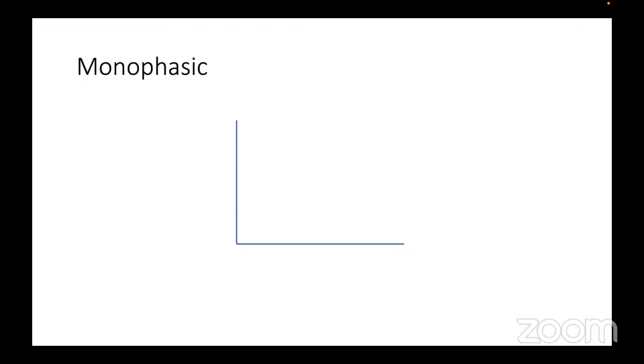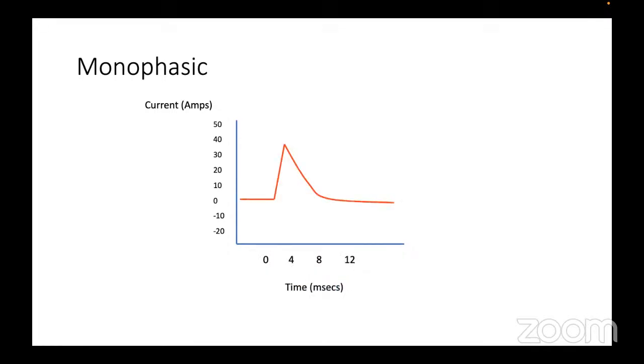Now you see that we have monophasic and biphasic waveforms. And when I was talking about the diode and the inductor, you have to see the inductor. Now that's diode, inductor, and capacitor. So the capacitor will charge the inductor, then the inductor charges the capacitor, and this circuit goes on. And because there is a diode in the circuit, the flow of current will be only in one direction. Okay. And because of this oscillation between the inductor and the capacitor, the current is not just a peak, it is spread over certain times, okay? And that's why it is called a damped sine waveform, because with every cycle of current, you will slowly lose some energy and it will slowly get damped. So that's why it's a damped sine waveform.